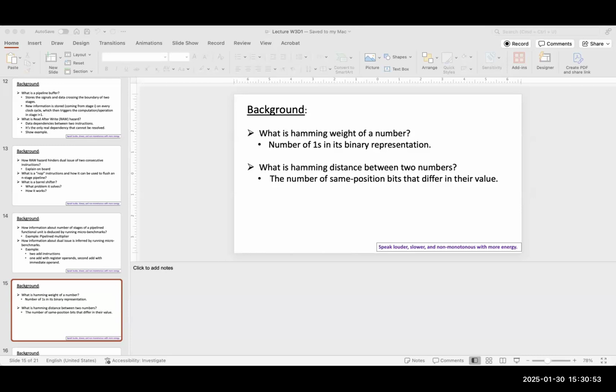So what is CPI? Cycles per instruction. Yeah, how many cycles it takes to execute an instruction, okay? Once you have filled the pipeline, after that you will have 1 instruction available on the output, right? So this gives me the information for the first instruction: how many cycles it takes to complete the multiplication. If it takes 4 cycles, and every stage I'm assuming takes 1 cycle, it means that in total there are 4 stages, right?